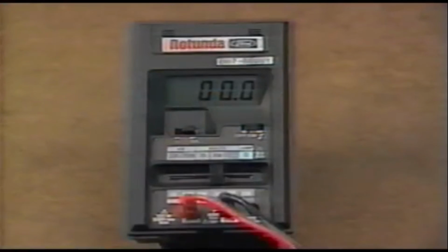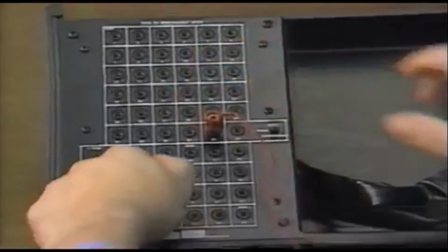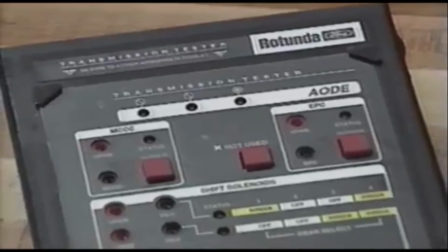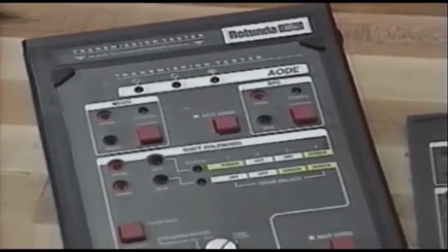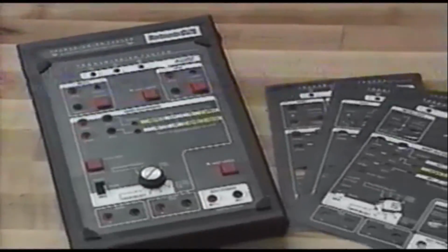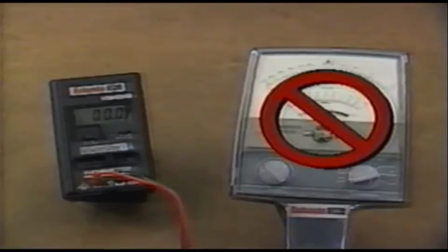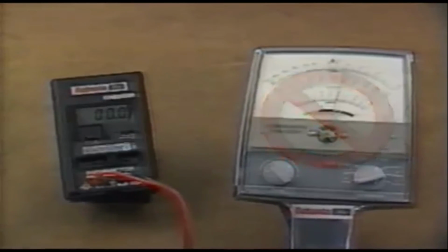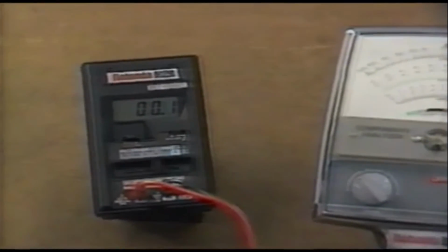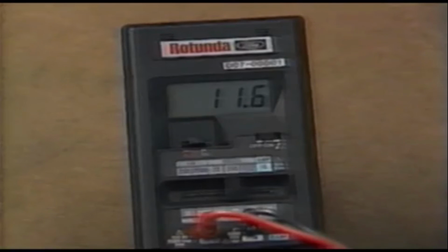A digital multimeter, or DVOM, an electronic control system breakout box, and some jumper wires, and the transmission tester are needed to make most of the tests you'll perform when diagnosing transmission, electrical, and electronic systems and components. And it's very important to remember to use a digital tester, or DVOM, when testing electronic circuits and components to safeguard against damage from excessive current that can occur when using analog-type meters.